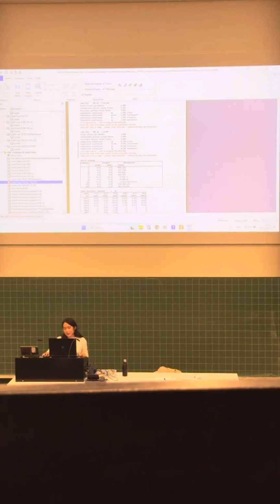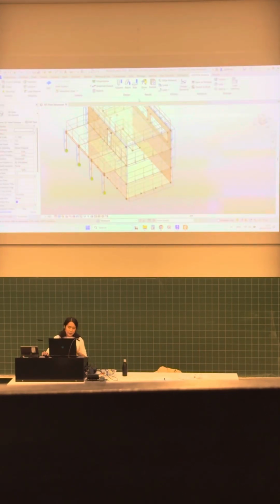So it takes a while, but this is one of the downsides, which I personally don't like with the load casing. But if you model it properly, it's quite easy because you know that probably the hole is problematic, so I will play with the boundaries, and with trial and error I will get it.